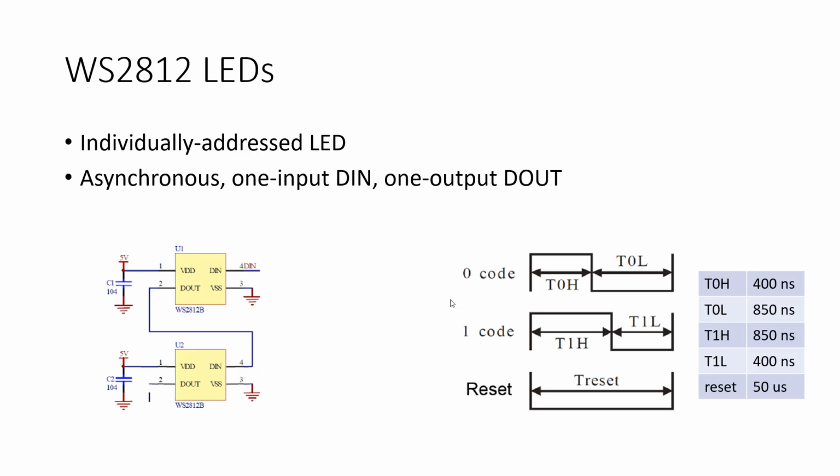So the way it works is they ripped off the Manchester encoding scheme, basically. The idea is that they wanted to create an asynchronous protocol for these. It was a bit serial asynchronous protocol. So basically they recreated SPI, essentially, right? Except they didn't want to put slave select, and they didn't want to put the clock, right? They wanted to create essentially a daisy chain, almost like JTAG in a way.